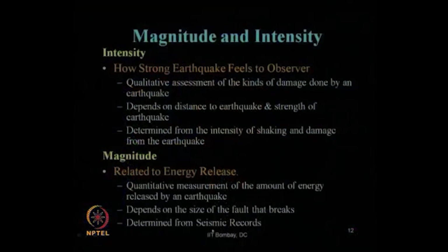Determined from the seismic records, whereas your intensity scale was measured by mostly taking the interview of the observer and looking at the damage of the structures. But this magnitude scale, if you can see over here, is determined from the seismic record. So, whatever records the various stations record of the ground motion, that determines what is the magnitude of an earthquake.